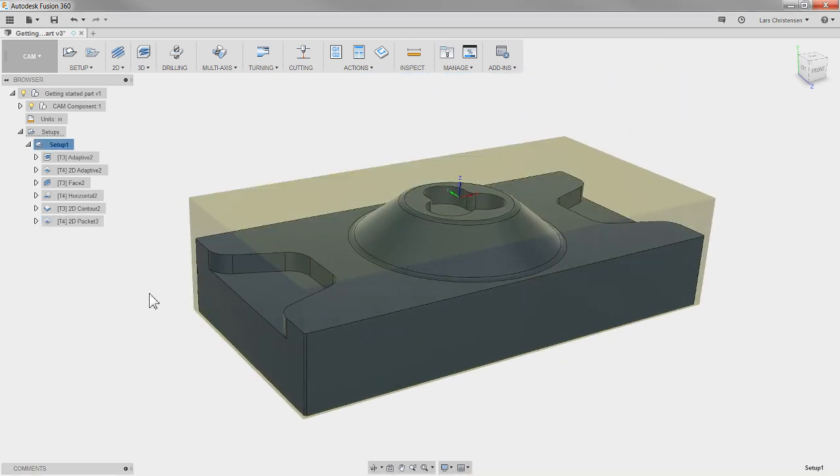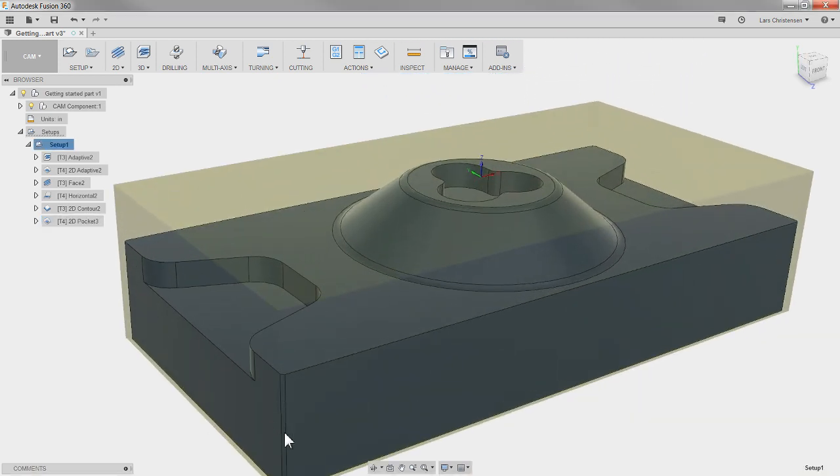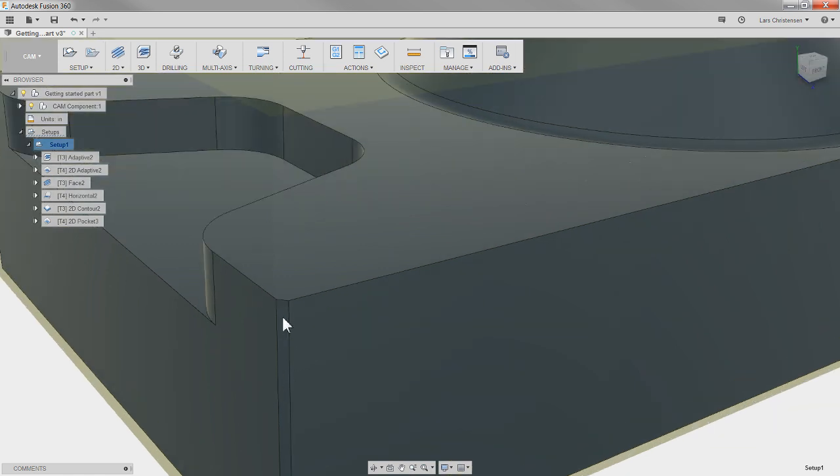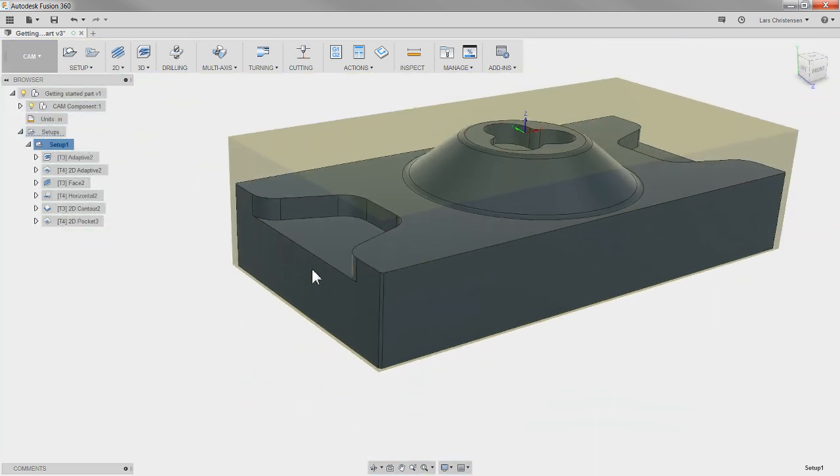What I always used to do was, first of all, see how I actually modeled in the chamfer? So that means that I don't have to worry about chamfering this one with a file afterwards. It's just like a 20 thousandths chamfer in here. So I always did that. Break the corners so you don't have to worry about that.